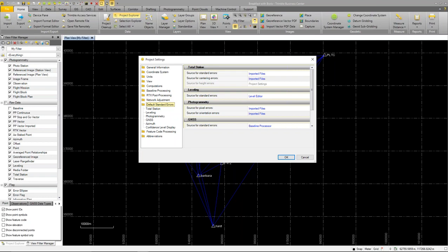It's hard to describe conditions that would be ideal for doing it, but I have seen networks that perform better, especially with the tilts that are calculated for the network in certain kinds of geometry, long linear kinds of surveys that run pure north-south and things like that, where it actually was better to let the observations take the adjustment than to try to perform one transformation for the whole thing.